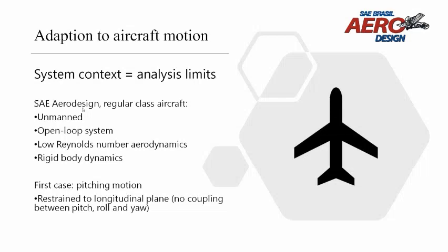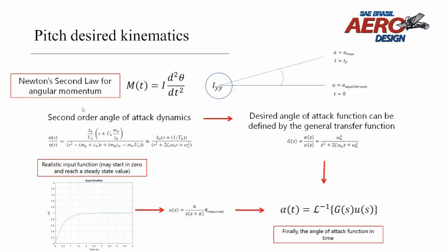Rather, the motion problem has to be converted into the rotation of a rigid body, for it is understood that aircraft should possess the ability to maneuver within a flight envelope. The first case of study will be longitudinal motion, keeping in mind that we are dealing with the decoupled equations of motion of a monoplane configuration. The new motion requirement is for the aircraft to rotate from its equilibrium pitch angle up to its maximum permitted angle of attack and maintain it as time goes to infinity.